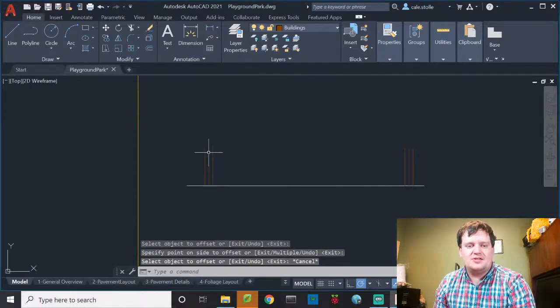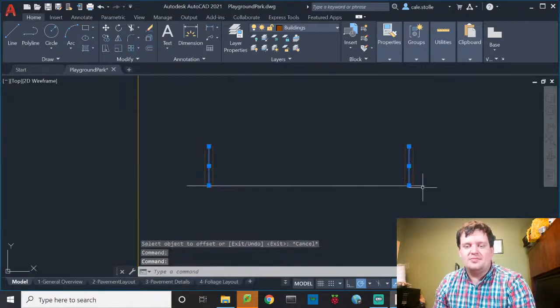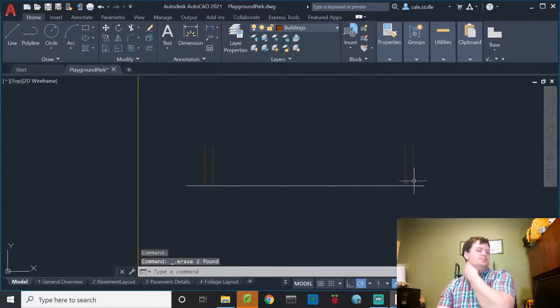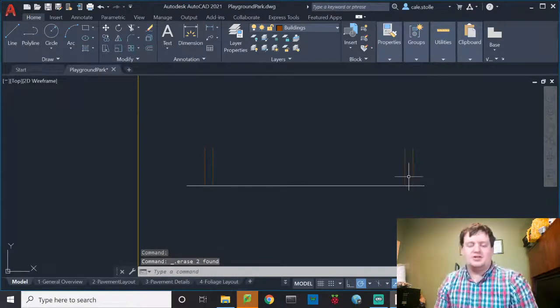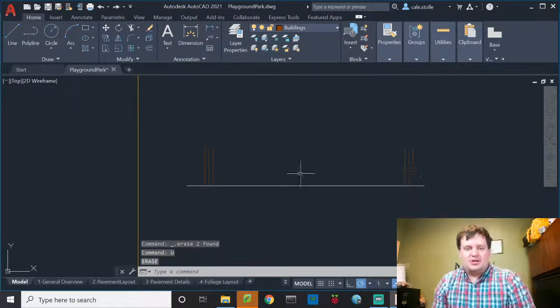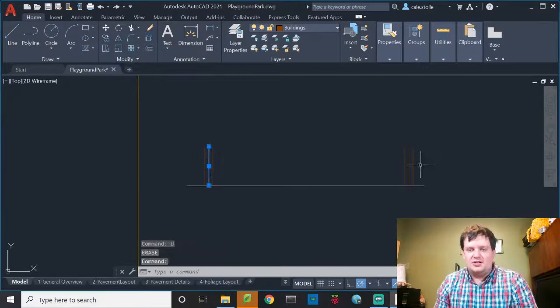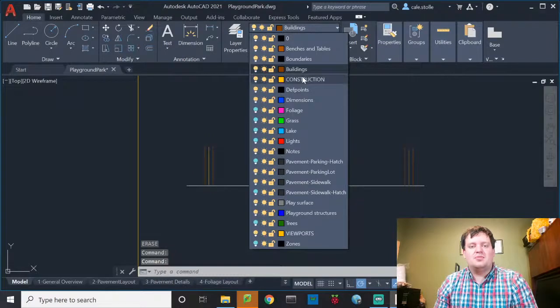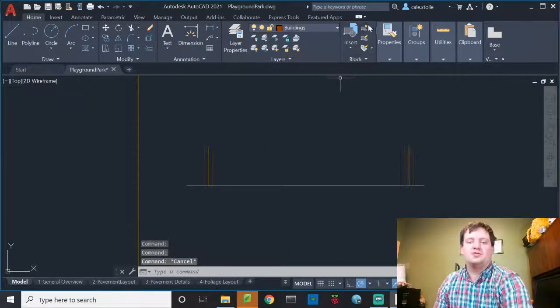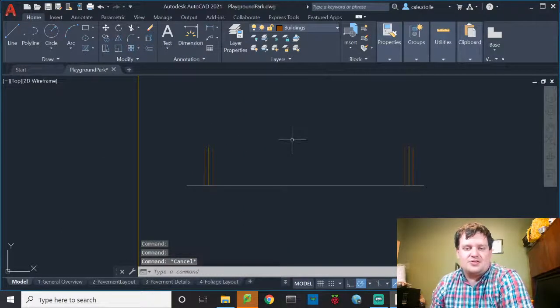Now this is my center line. I don't need it anymore. I'm deleting it. I shouldn't have done that. I'm going to convert this into a construction line. That way I'll keep it. It won't print, but it's something that I can measure and work from in the future if I need to go to the center of that.